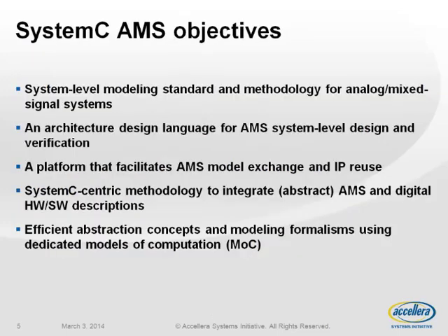standard. What are the objectives of SystemC AMS? At the end, like SystemC, we are targeting system level design, but then for mixed signal. There are other languages out there like Verilog AMS and SystemVerilog, which are much more addressing the verification and implementation domain. With SystemC AMS, we're really addressing the system level modeling domain. We would like to create architectural designs and do architectural exploration using SystemC AMS. And as this is based on C++, it also facilitates a good platform for model exchange. So not only for digital, but now also for AMS.